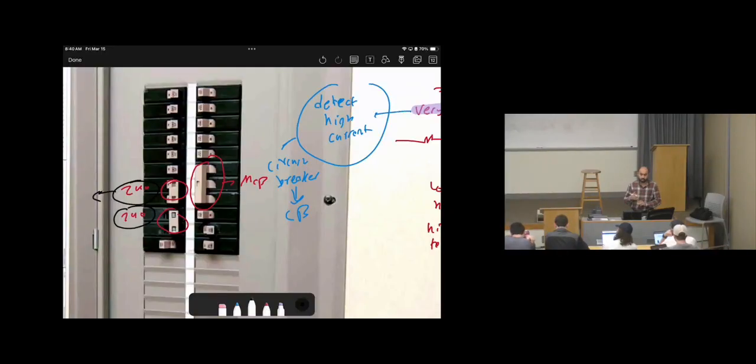Okay, again, what's the point of using 2 voltage systems? Why didn't we use 120 and stop? Because sometimes some devices consume a large amount of energy, and 120 might not be sufficient to supply this. Then to get better performance, we need a higher power level, because we know the power is V times I, right? So let's increase V, double V, then we can get a higher amount of power, right?